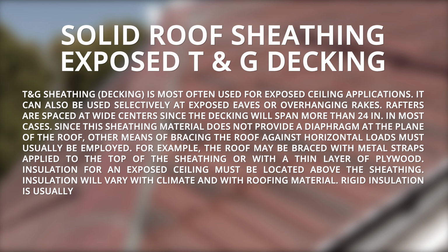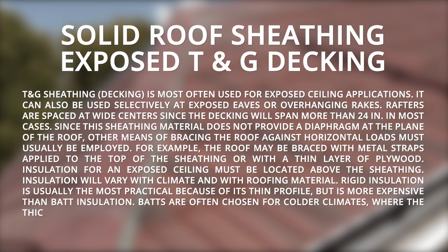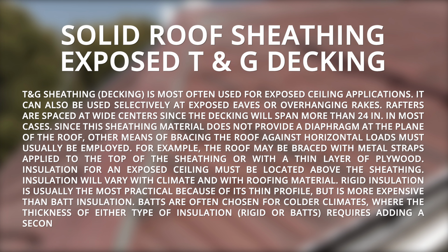Rigid insulation is usually the most practical because of its thin profile, but is more expensive than batt insulation. Batts are often chosen for colder climates, where the thickness of either type of insulation, rigid or batts, requires adding a second level of structure above the decking to support the roof.